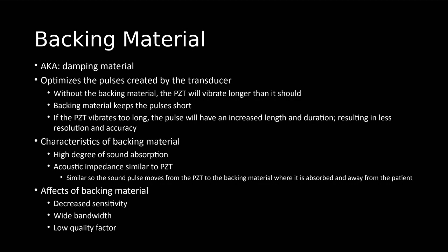We don't want that. So the backing material is going to keep those pulses nice and short, kind of like just a piano key, right? You're just striking a piano key and that's it. So if the PZT vibrates for too long, the pulses are going to have an increased length and duration, resulting in decreased resolution and accuracy, which we know we do not want. So there are certain characteristics of backing material. It has a high degree of absorption, so it's going to absorb all of those lingering frequencies so that it doesn't vibrate for too long.